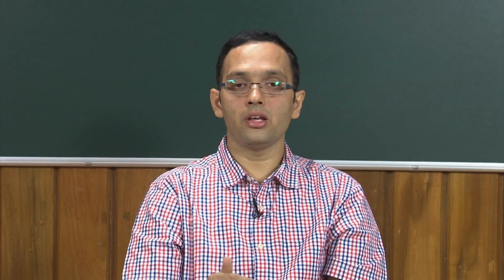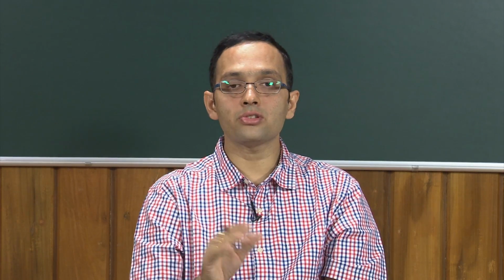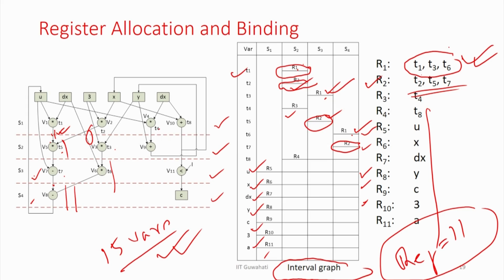If I told you you can use 4 multipliers, still you can do that, you can use 6 multipliers and do all the operations differently, that is also possible, but which one is going to have fewer resources, and the interconnection also depends on this kind of mapping. Similarly, for register transfer this mapping can also be different. So, instead of T1, T3, T6 I could have stored T1, T5 and T7, that I could also have done. So, there are other possibilities.